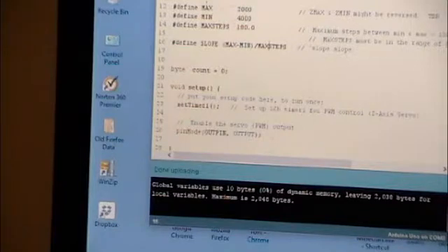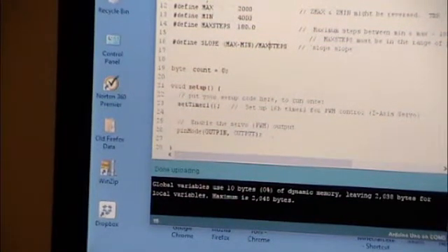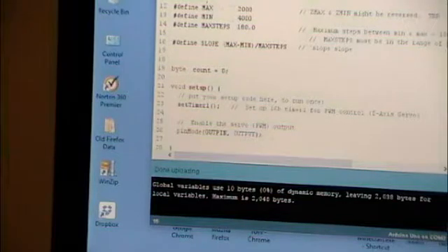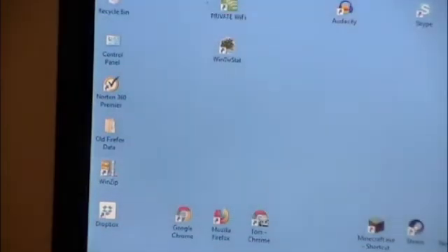If I put a second one on here, you won't break your computer, but there's a current shut off in there that says, oh my god, that's too much, and it'll just shut you off. And then your stuff won't work, and you'll be wondering, why doesn't this work? It's because you're drawing too much power. And that's all we're going to talk about servos and PWM tonight. And I'm going to unplug this guy.